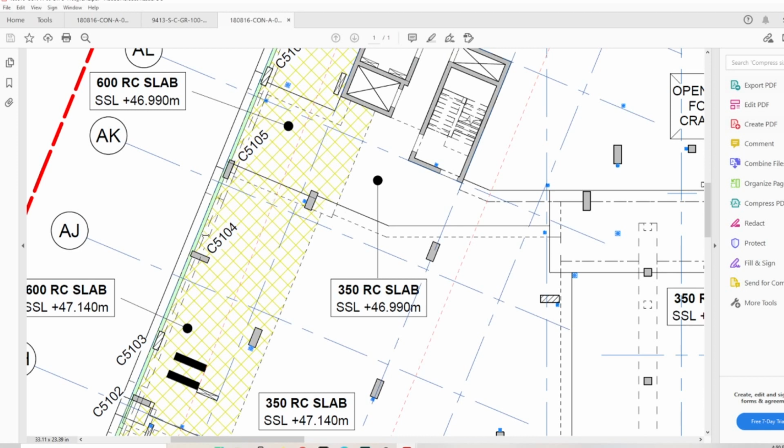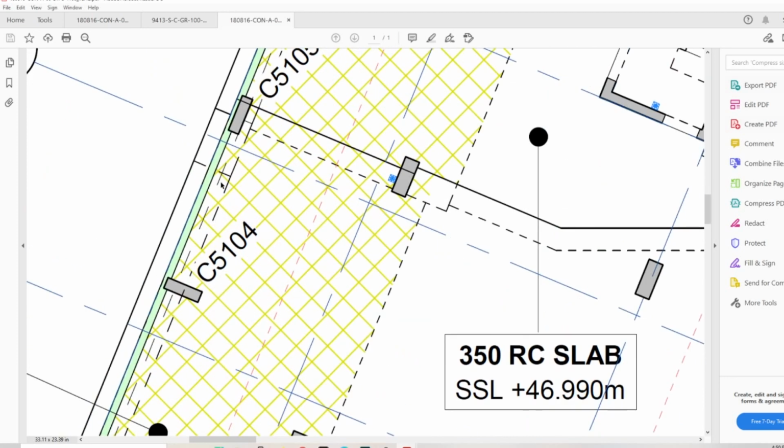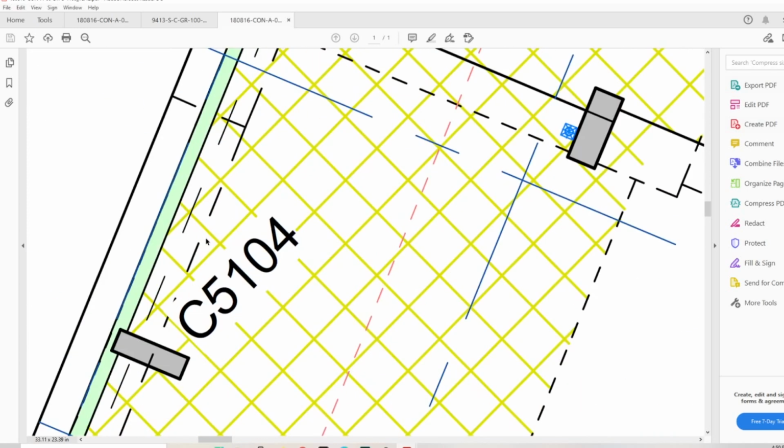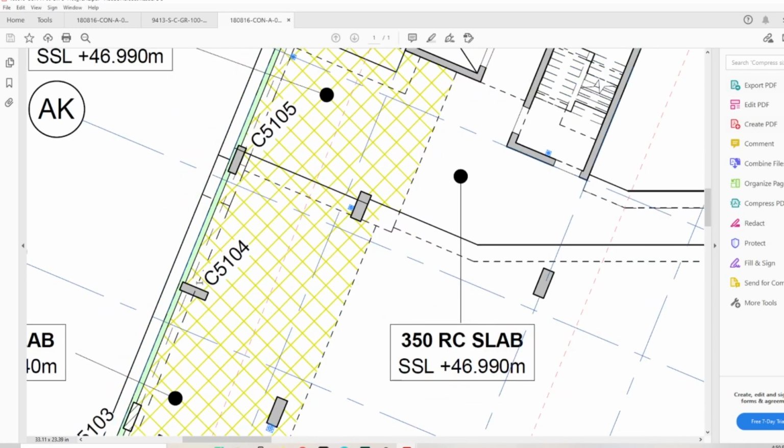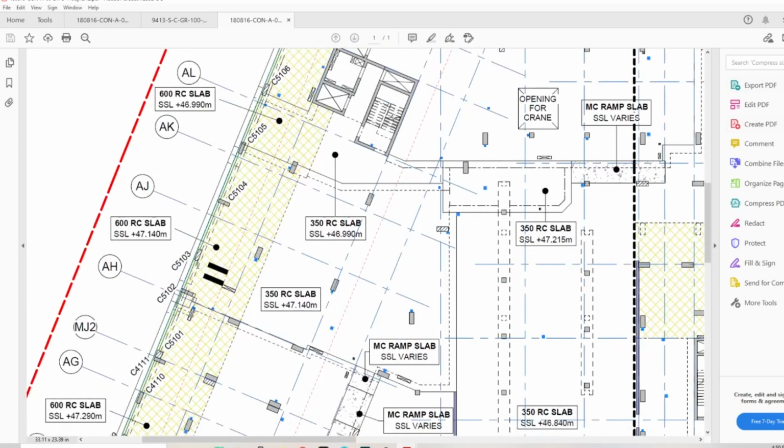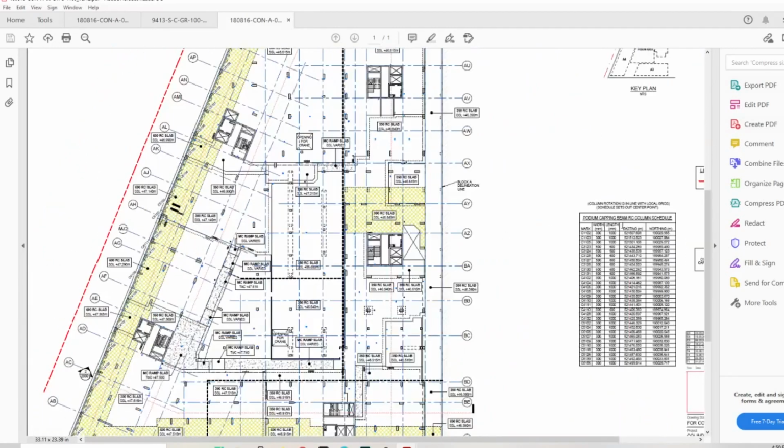Same here, this one of these dashed lines, this internal dashed line, is going to be our capping beam, and this dashed line is the liner wall. So our capping beam goes up to here, just in this case in temporary condition going to be poured back to this line, but later all this width is our 1080. So we know there will be columns here, and we got information on this drawing. Yeah, so this is quite alright.